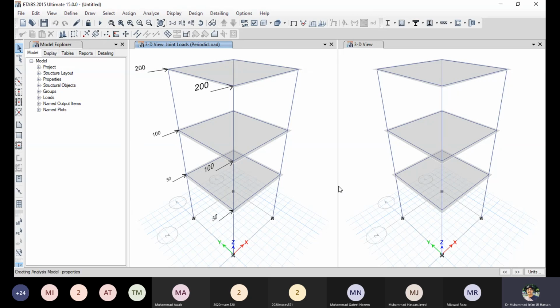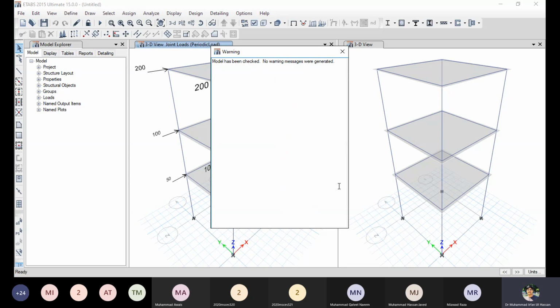You can play with different things by changing the bottom restraint or adding shear walls when you apply the time history earthquake function. These things are important whenever you are analyzing a building in a high seismic zone. You should analyze it as a time history. The time history of the actual earthquake record should be obtained and applied. You can check the peak response and peak displacement of the structure, because there are guidelines given for displacement. So whenever you are doing performance based design for structures, you need this method of analysis.